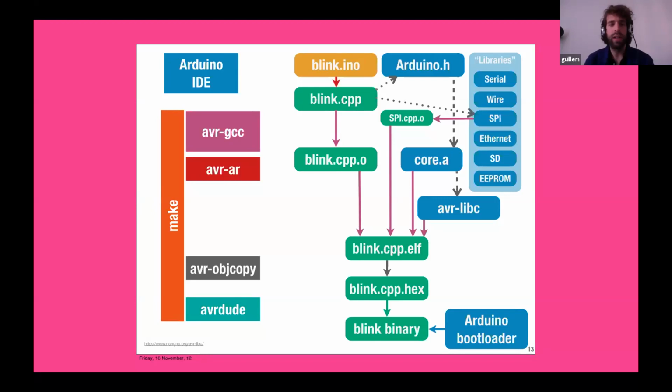So going back here, we are on C code, so let's see how C code is built and how we use it ourselves. If you use C code, but you code in an Arduino environment, your file is not going to be called .c. It's going to be called .ino, like blink.ino, from Arduino, of course. And so what happens when you get that file that says void setup, set digital pin mode, let's say 2 as an output, and then you go to void loop and you say digital write this pin high, and do something, and then the other.